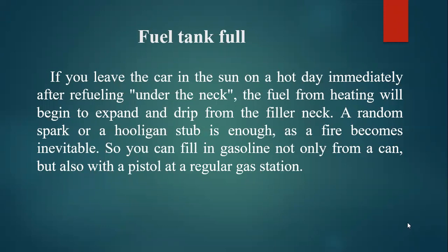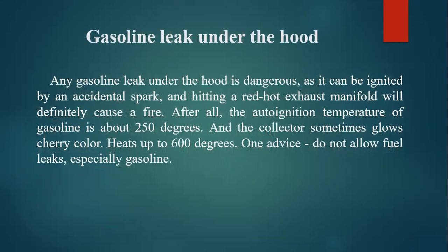Next. Gasoline leak under the hood. Any gasoline leak under the hood is dangerous, as it can be ignited by an accidental spark and hitting a red-hot exhaust manifold will definitely cause a fire. After all, the auto-ignition temperature of gasoline is about 250 degrees, and the collector sometimes glows cherry color. Heats up to 600 degrees. One advice: don't allow fuel leaks, especially gasoline.